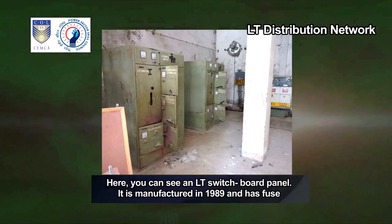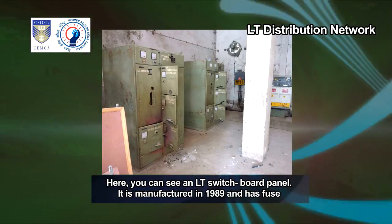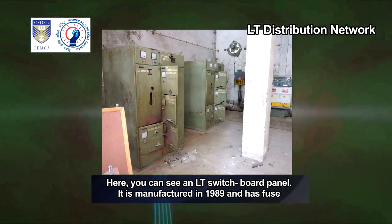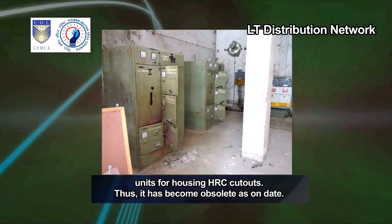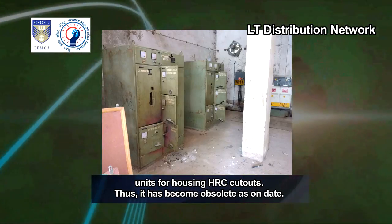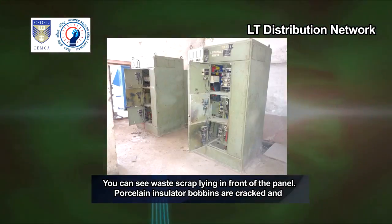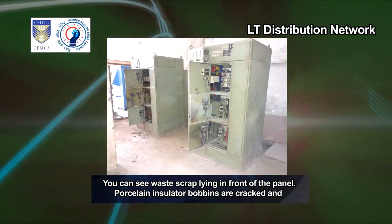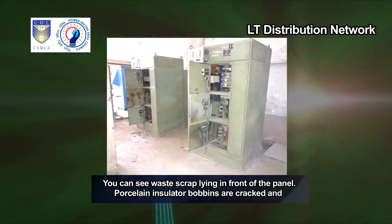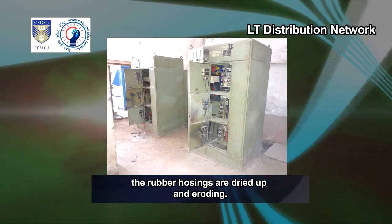Here, you can see an LT switchboard panel. It was manufactured in 1989 and has fuse units for housing HRC cutouts. Thus, it has become obsolete as on date. You can see waste scrap lying in front of the panel. Porcelain insulator bobbins are cracked and the rubber housings are dried up and eroding.